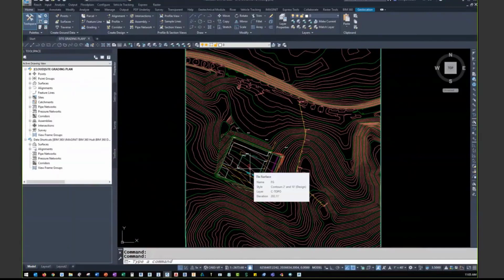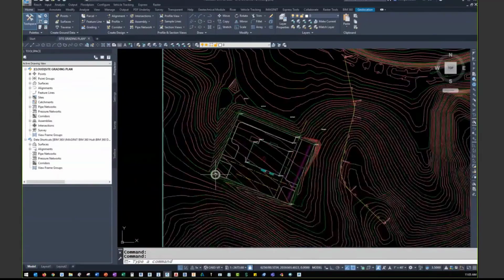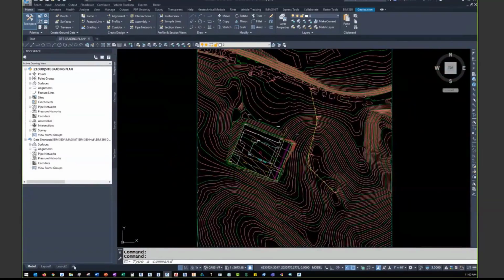I've added maybe another access road or some other content there. And I would be publishing out a new shared coordinate because that building spot, that reference point, has been moved from the original location a little bit farther back. I've got a new graded surface around that, so I'd be publishing out another surface to share. And then I could go into Docs and answer that issue.